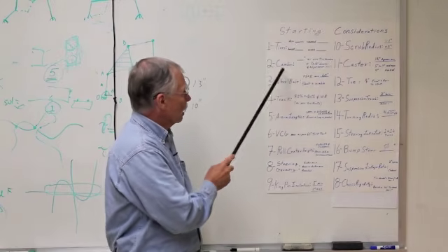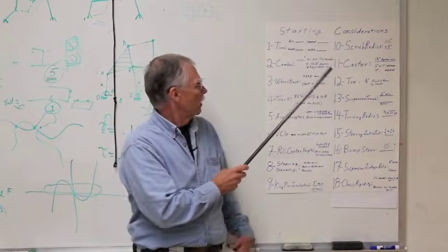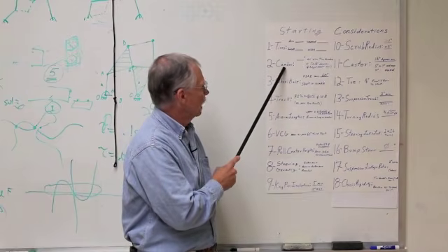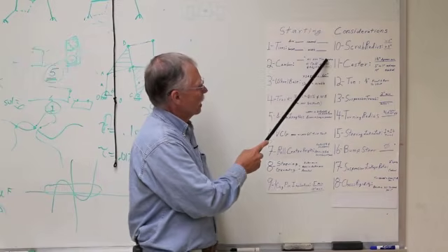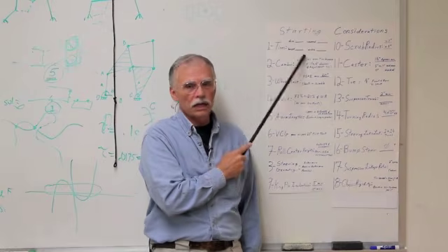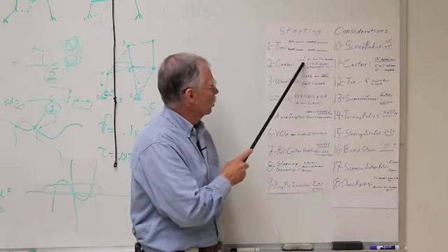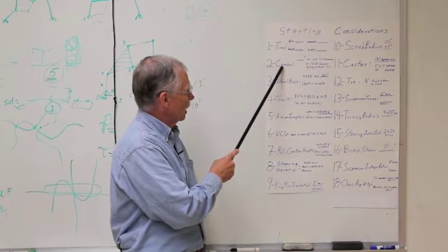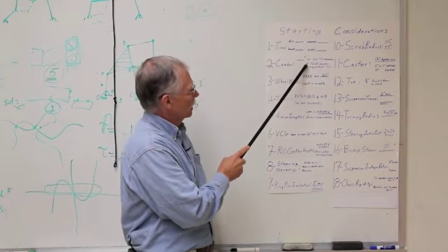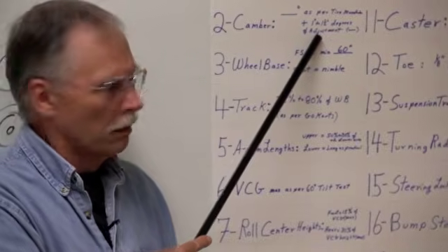Now, continuing on, the first geometry setting we need for the tire is camber. We get that as per the tire manufacturer will have a number of degrees which his racing tire will work best. That is your target camber setting. However, you have to design in an extra 1 1/2 degrees of adjustment minimum.